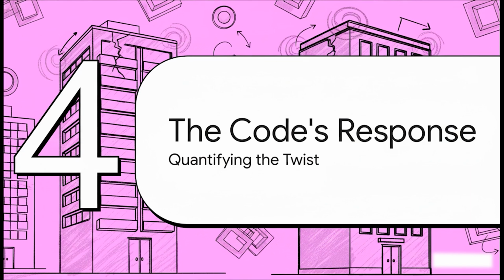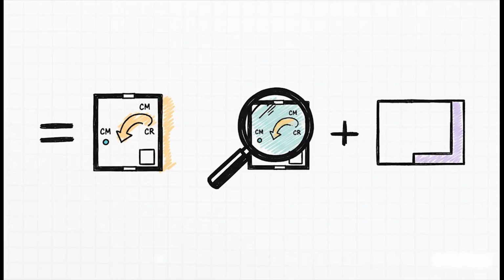Now, in response to these kinds of devastating failures, engineering codes like India's IS 1893 got a lot stricter. They give us a clear, mathematical way to force designers to account for torsion whether they think they need to or not. The code's main weapon is this formula for design eccentricity. And the key idea here is actually pretty profound. You don't just design for the twist you can calculate on your computer. The code makes you design for an amplified, worst-case scenario.